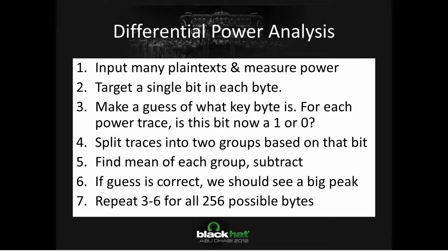So one thing you're going to say next is, that example you just did was a 4-bit device. A, that's stupid because you could guess that in 16. But B, we still have 128-bit keys, so where does this help us? Because we can't guess 128 bits. The point of DPA, or all of these side channel analysis, is that we're going to be targeting algorithms where at those intermediate values, you can easily split off the key 1 byte at a time.